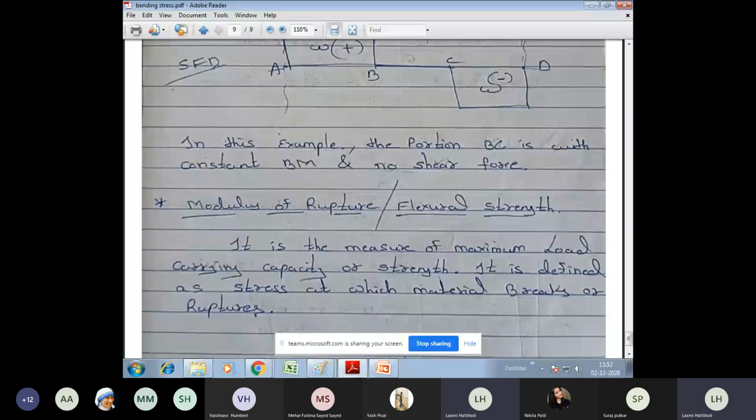If I give you a beam, first of all, you should know how to calculate the bending moment. After calculating the bending moment, you should calculate the inertia. Then you should calculate the Z. What is Z? Section modulus. If all these quantities are known to you, then you can easily calculate the M dash value, because I have told you all the formulas now. With this background, we'll continue with the numerical examples in the next class.